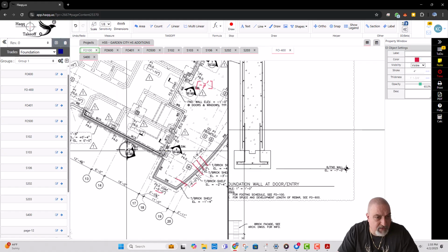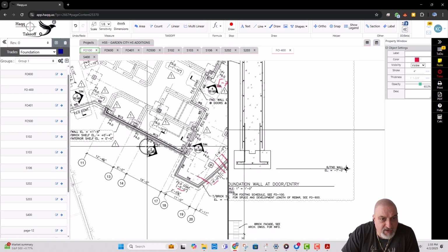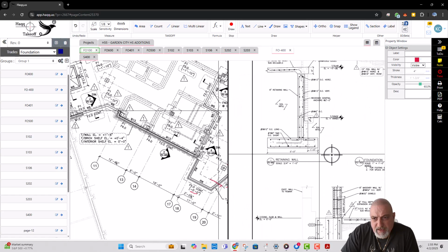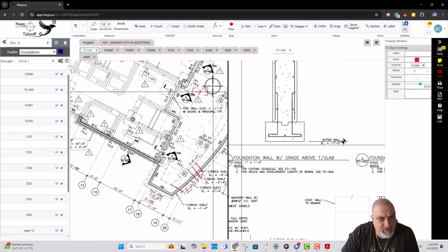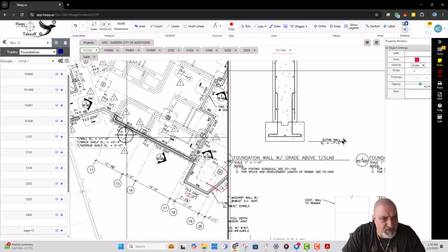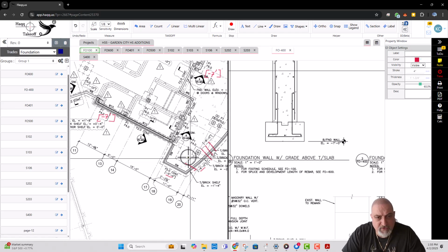Same thing here. Let's take a look at section 2. What is at the exterior, this wall section? Section 2 shows -7 as well. So we had -7 here, and then we come here. Let's click the B brush, -7 feet. That's the bottom of footing. And then we had -5 here. So -7 to -5, we need 2 steps actually.